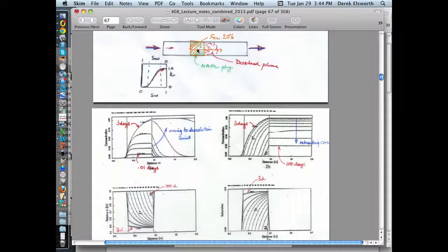You have it sitting here at some saturation. You should be able to calculate what the relative permeability would be at this particular saturation. If you know the relative permeability at that saturation, then you'd know exactly what the actual permeability was. And if you know that permeability, you'd know what the volumetric flow rate is because it is given by this. So if you knew what the gradient across this was, you knew what the permeability of this soil was, and you knew the relative permeability as a function of saturation from a curve like this, then all of a sudden you can calculate the flow rate.